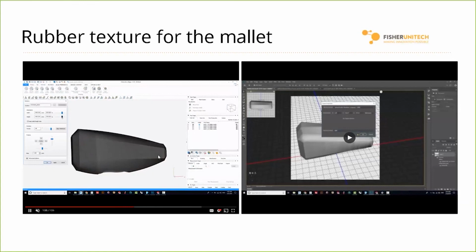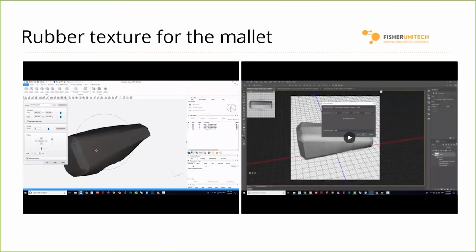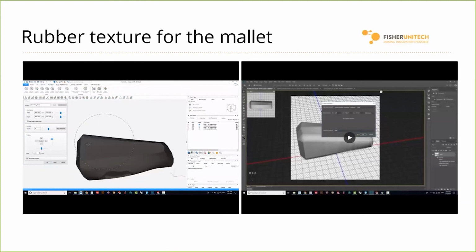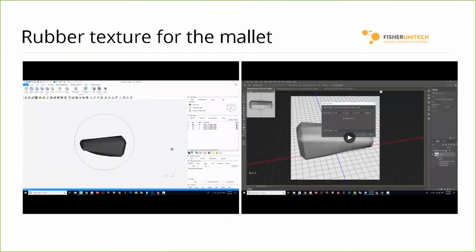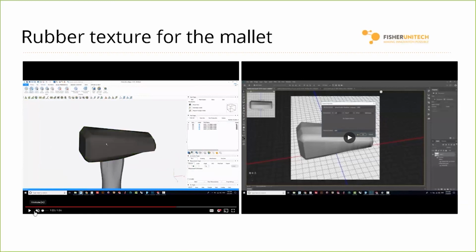You can scale it, rotate it, move it, and when you find something that you're happy with, you can just apply it and hit OK. So this is a great tool, but it's very limited. Like I was talking about these different methods of projecting your UV map before, this is very, very limited. You can really only do a straight projection or a cylindrical projection.